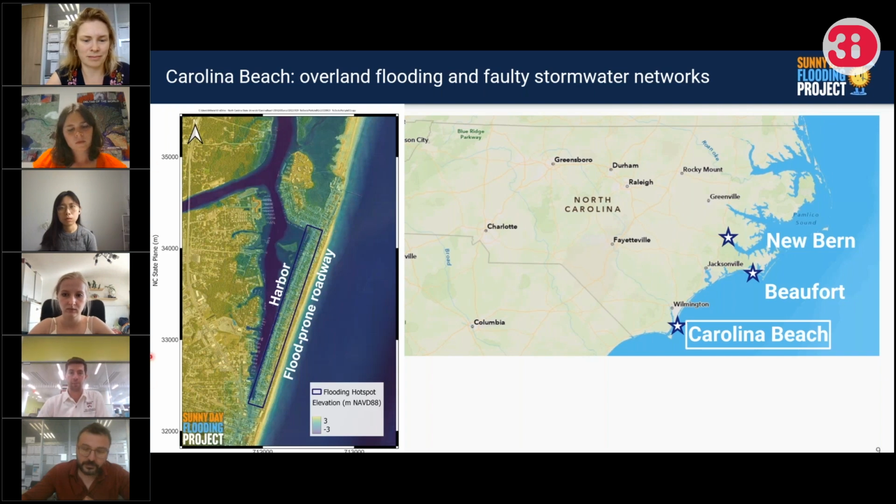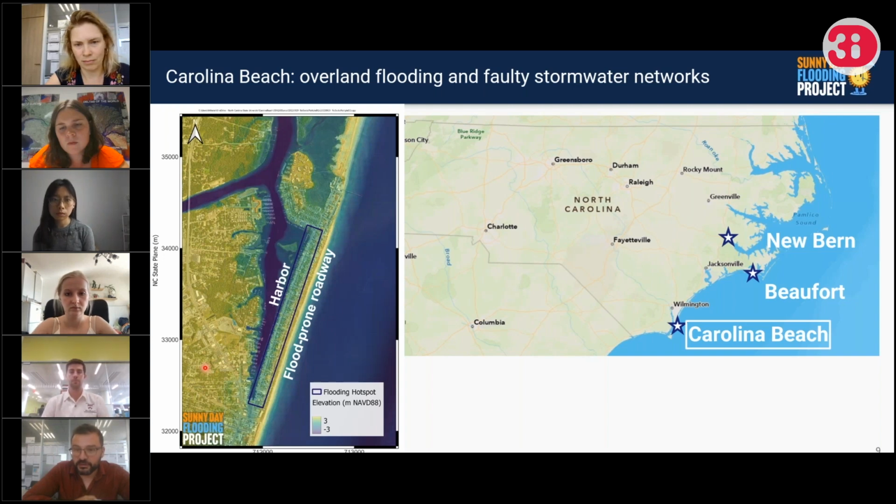No, I have not heard of that Python package. What did you say it was called? It's called Open River Cam. So maybe it's something you can also try out, because then you will also have the flow velocities at that point. You only need a camera. It doesn't need to be a very expensive camera with a special lens or something like that. Then you just calibrate these packages under some parameters, and then you can have the flow velocities. It's a very nice open source package. Yeah, that's a good suggestion. I'll definitely look into that. Thank you.